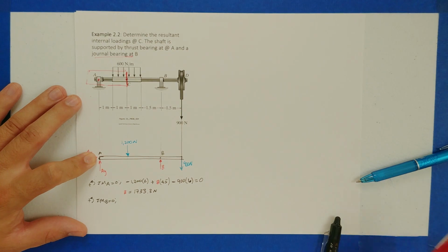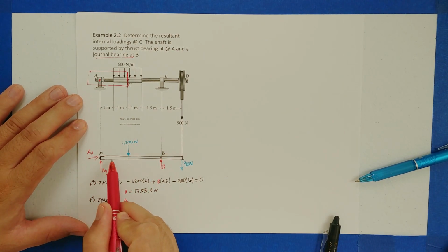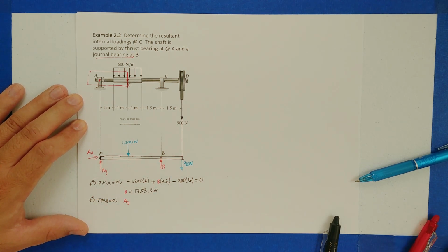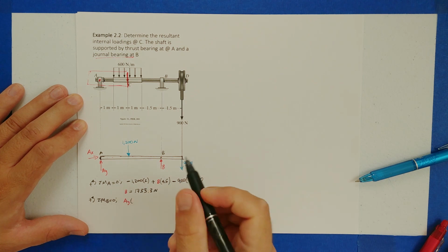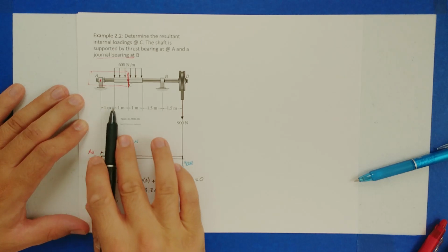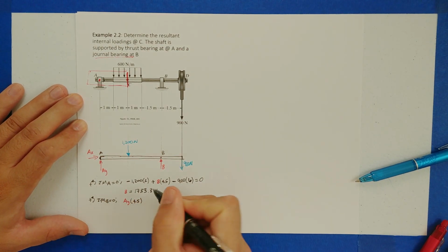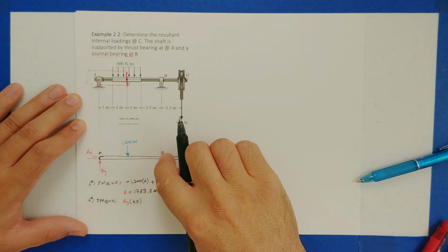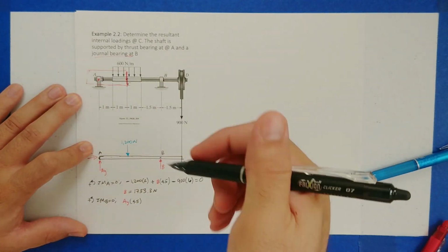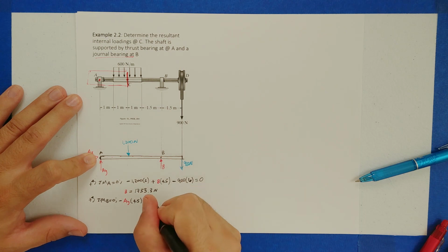First I'll start with our reaction force AY. Notice AX crosses, right? Its line of action is through point B, so it's not going to generate a moment. Only AY, right? We said the distance between A and B was 4.5. Let's check again: 1, 2, 3, 4.5, 4.5. And if I'm pinned at point B and I push up, it'll make it rotate clockwise, so that would be a negative moment.